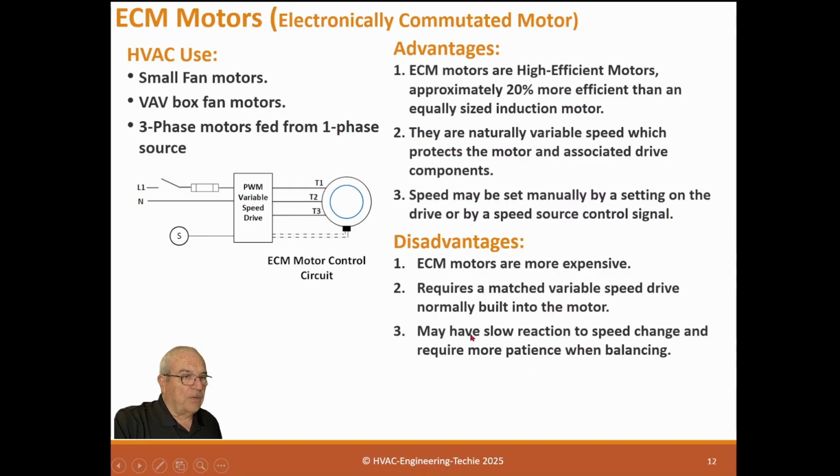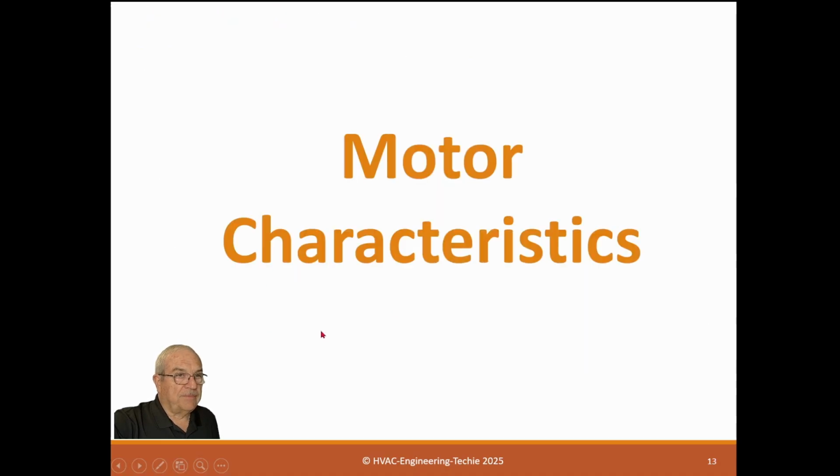The other little problem I've seen is because the motor is mated to the VFD, buying motors is more difficult because you normally have to buy the whole assembly, but you can buy the motor separately, but it has to be an exact replacement motor. You can't be switching motor and drive together. They're a matched pair, so you have to buy them that way. So they're a little bit more difficult for maintenance if you need to replace a motor or a drive.